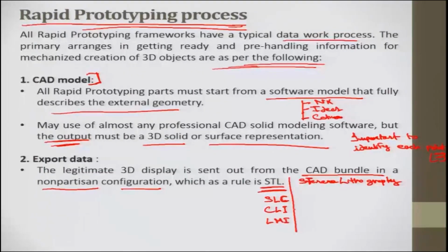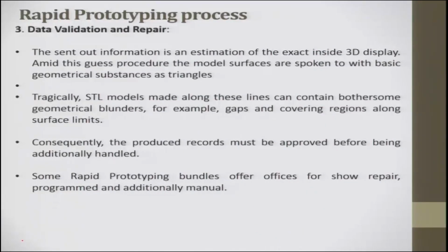For instance, CLI is common layer interface, LMI is layer manufacturing interface. So it can be stored in these formats also, depending upon the requirement of the machines, but most of the machines these days support STL format. So the next step is data validation and repair.